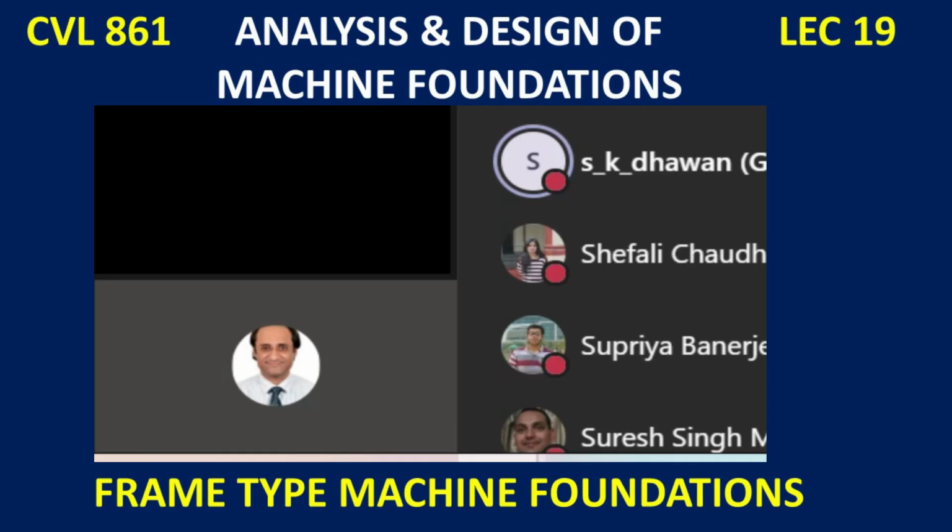Now, the basic thing I would like to share further is equilibrium and the section force. In an RCC building, the load goes to the beams, then columns, then to the foundation, and finally to the soil. Likewise, for section force, we need to know the actual forces: shear force, bending moment, torsion, and the application of external force.